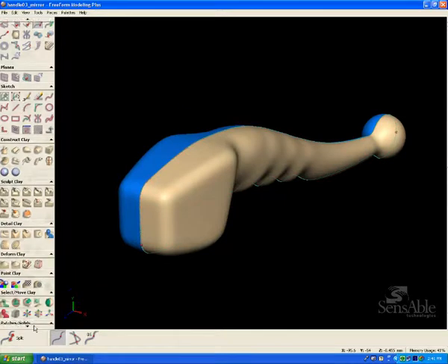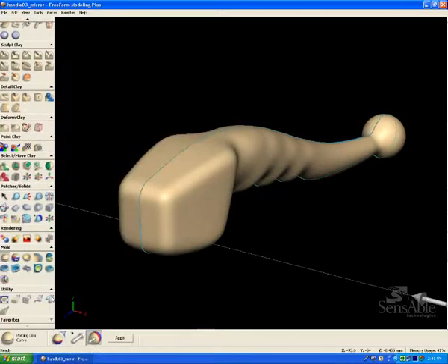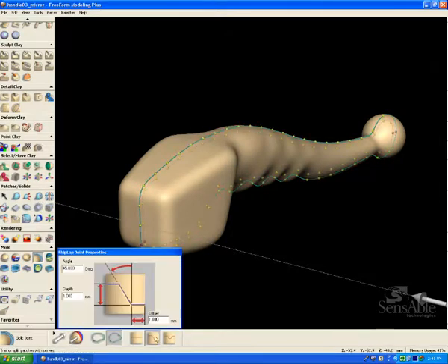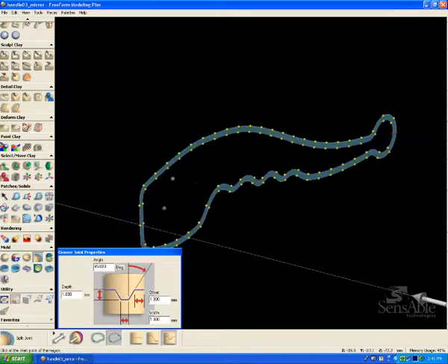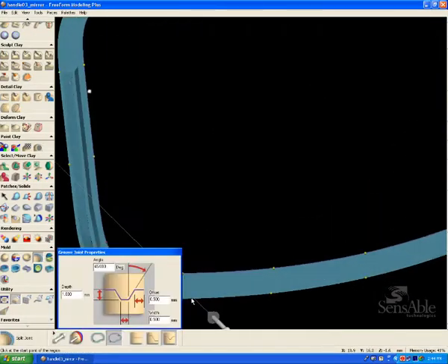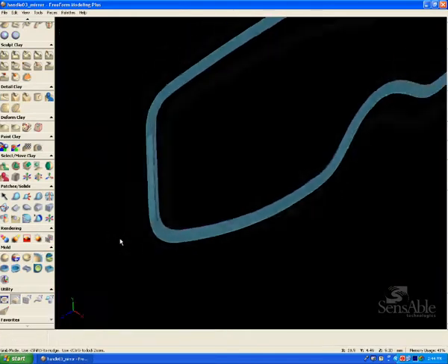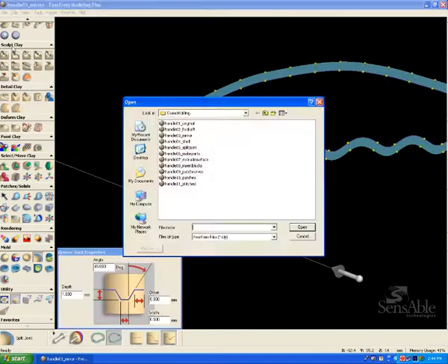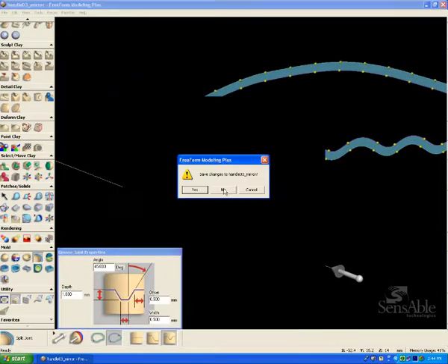So there's areas of like a dovetail where the two parts will force themselves together in the right position. It's not just flat against flat. There are joints. So I'm just adding angles and the depth for the shape and the size of these groove joints. So I just go along the edge, and you can see I'm adding that groove where the parts will come together. I can go ahead and edit the angle. The angle is a little steep right there, so I might want to get rid of that and knock it down a bit.